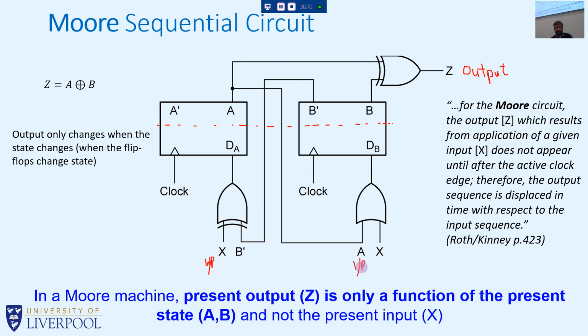So that's pretty important, to be able to look at a circuit and figure out what are the present states, what are the next states, what letter represents the output, and what letter represents the input. Maybe there are multiple outputs and inputs, okay? And we have our next state combinational logic and our output combinational logic, okay?